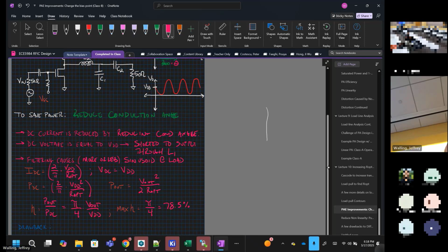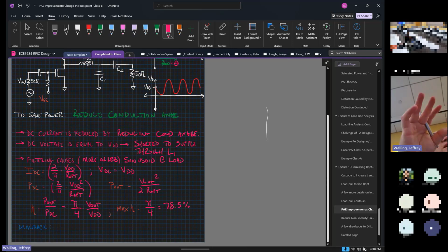All right. Now, when we're talking about analog audio amplifiers, the Class B is not necessarily a very good amplifier because it has a lot of distortion in the output wave. In particular, crossover distortion, where if I'm doing a push-pull, one of the push-pull devices doesn't turn on quite when the signal gets up to the bias point. Takes a moment. It causes just a little bit of crossover distortion.